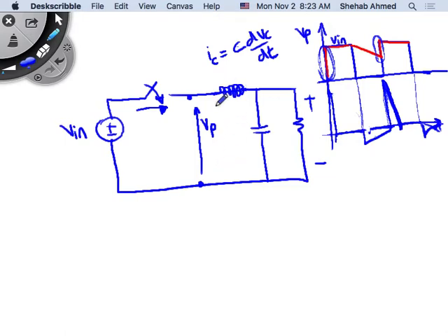But after adding this inductor, what happened? We know that inductors force or maintain current continuity, right? So if I add this inductor to maintain current continuity, and then I have a switch before it that I'm opening instantaneously, we know that inductor voltage equals L di/dt, right? So if I try to instantaneously disrupt inductor current, which is equal to switch current, I will develop a very large voltage across the inductor, right?